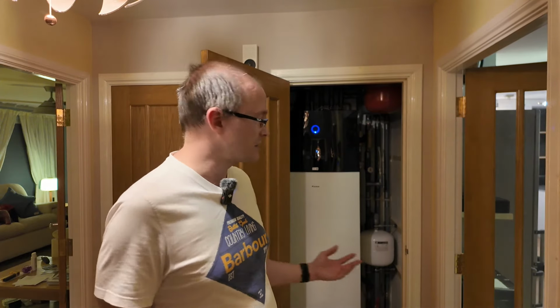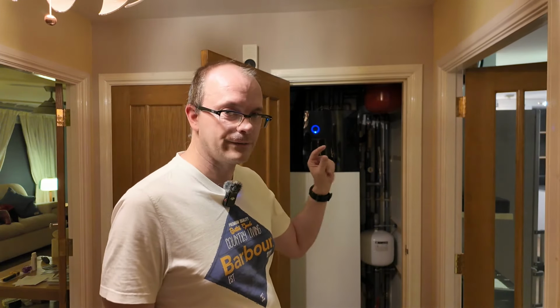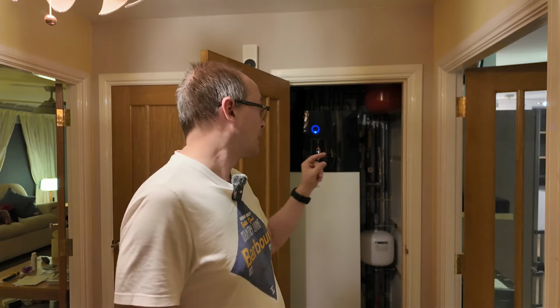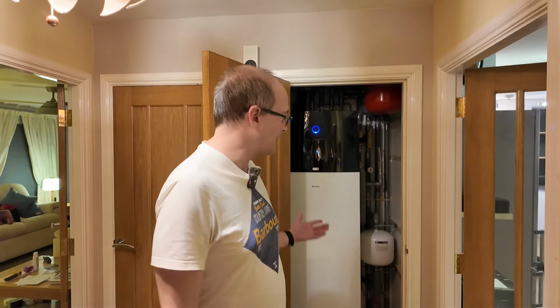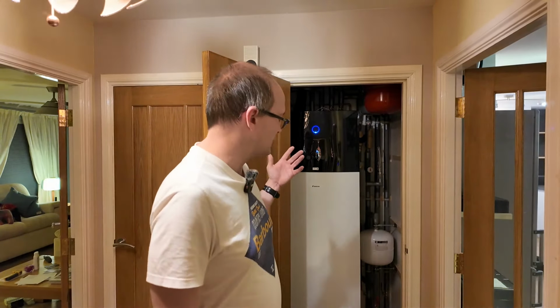I am wondering whether we should simply switch off the disinfection cycle and just have a manual set point of 55 degrees Celsius on one particular night using a regular schedule. That is entirely possible. So all told, I think the tuning for my heat pump is around about 95% good.